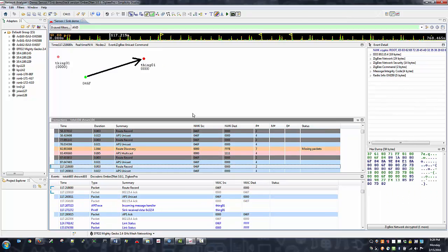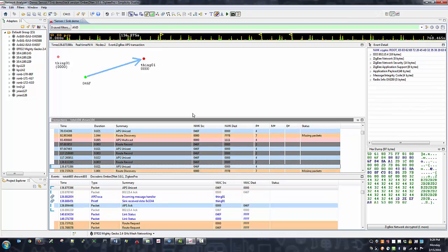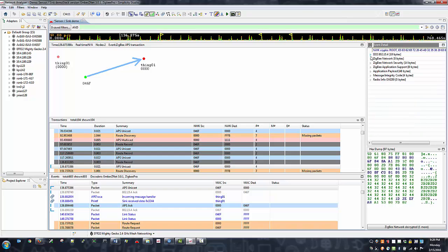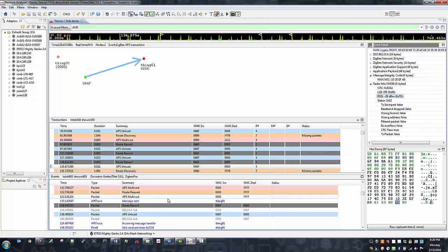More than just a packet sniffer, Simplicity's network analyzer works with Silicon Labs' patented Packet Trace Interface, or PTI, peripheral on its wireless chips to provide direct feedback from the baseband radio of each device, allowing any supported Silicon Labs radio to report detailed packet transmission and reception data, such as timestamps, link quality or LQI, receive sensitivity or RSSI, and CRC pass-fail results, all without any software overhead.